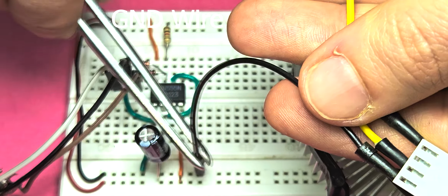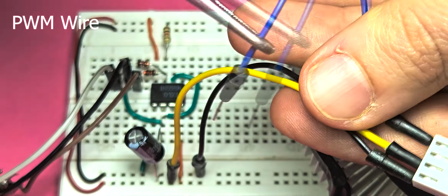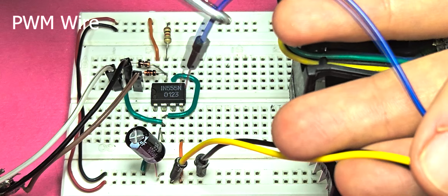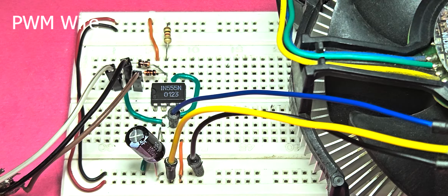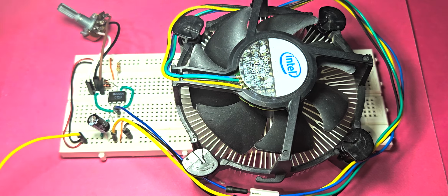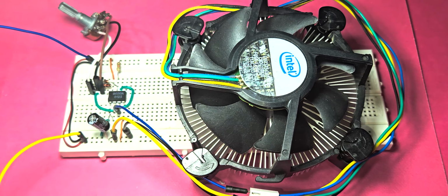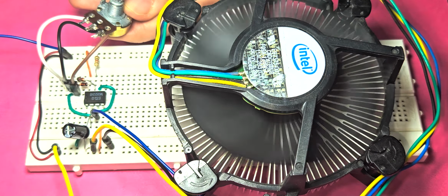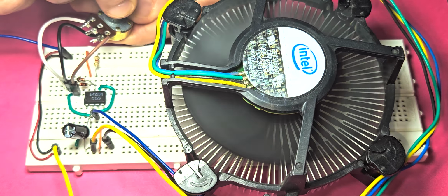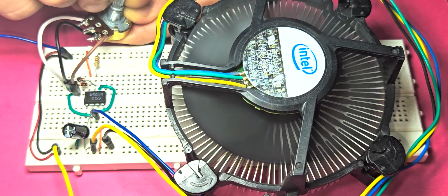In this phase, first, using IC 555 in this circuit, PWM pulses are generated in pin 3. These pulses are connected to the fan's PWM base, which has a blue wire, to control the fan's speed. As explained, in this case the frequency of the produced pulses is fixed and only the duty cycle of the pulses will change, so the average voltage applied to the fan will change and the fan speed will change.